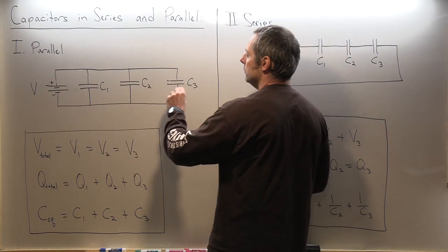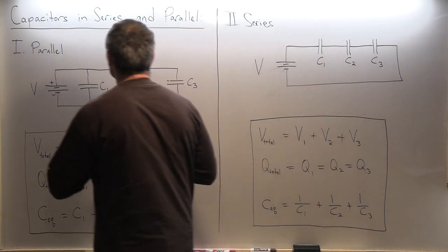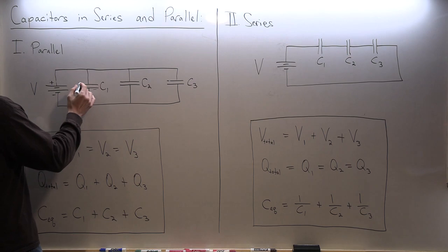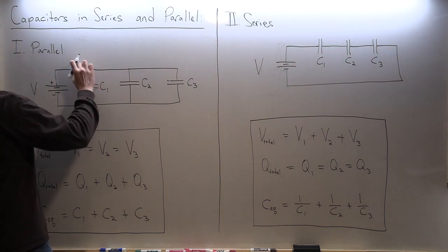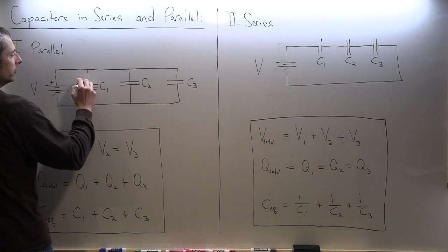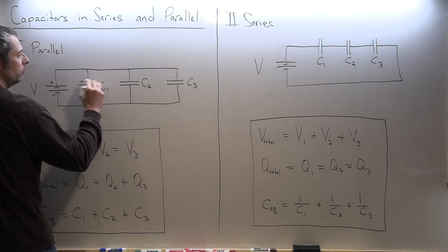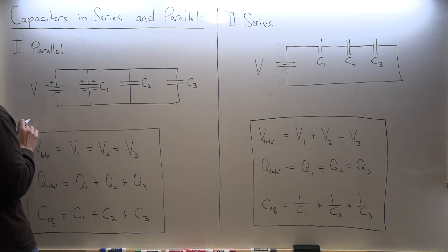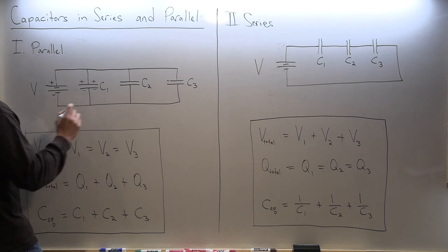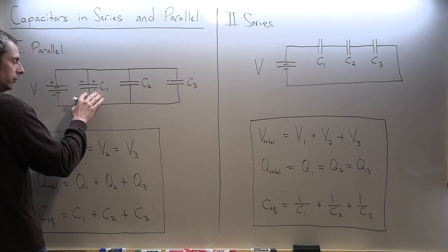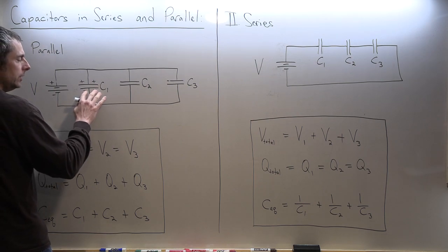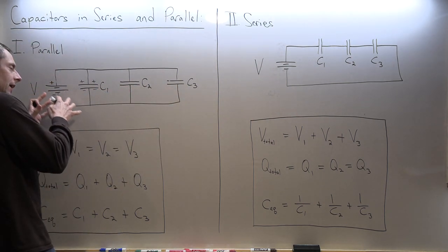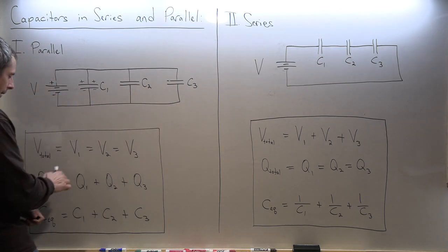And then of course, when we charge this with, say, 2 electrons, that means 2 electrons have to come out of this side. That's how a capacitor works, leaving this side with a deficit of 2 electrons, in other words 2 protons that are unpartnered. So we might have, let's suppose, 2 here, maybe 3 here and 5 here. That's a total of 10 electrons that went through the battery.